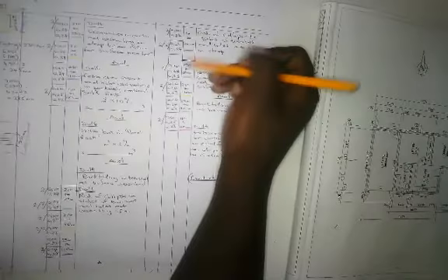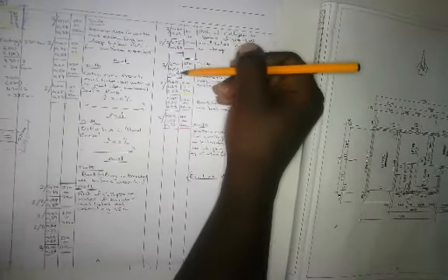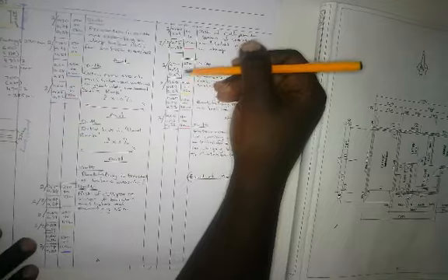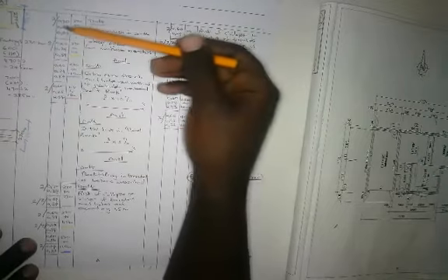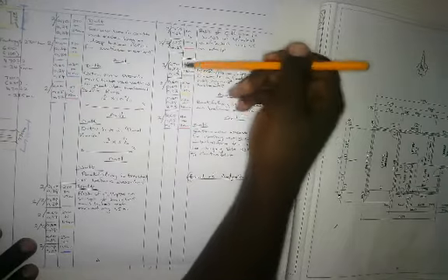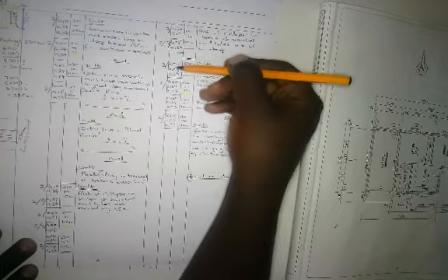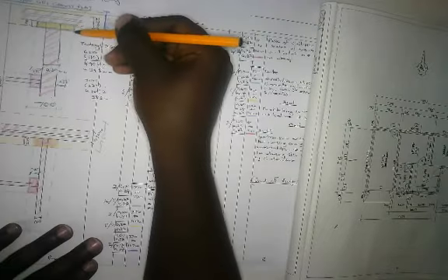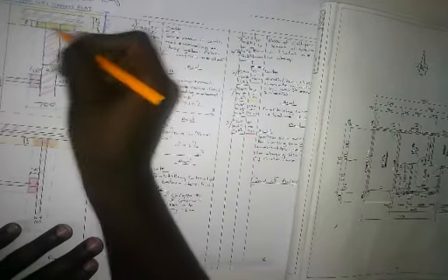So the same thing applies to all the other walls where they butt against each other, and then you're going to deduct your concrete footing, because remember, we are adjusting. We are not going to do a double measurement for concrete here, because we're taking out the soil. We're also going to take out that piece of concrete we put there. So it's still going to be the same dimensions. The difference in this case is going to be the thickness of your footing.